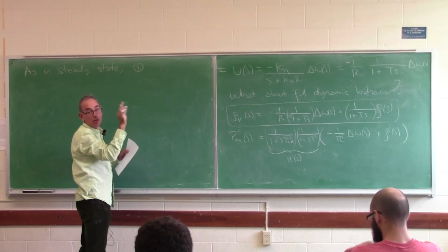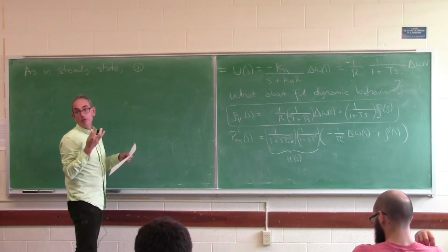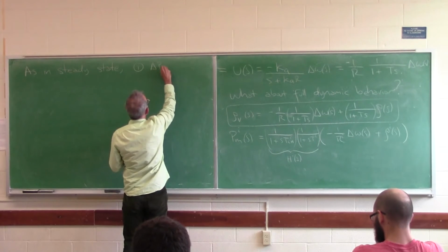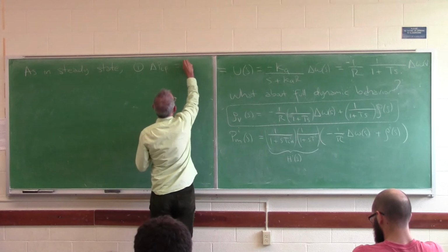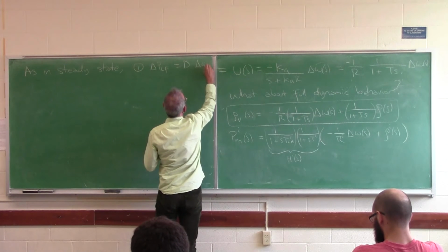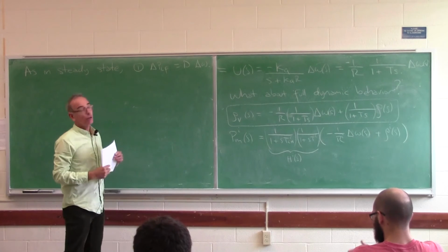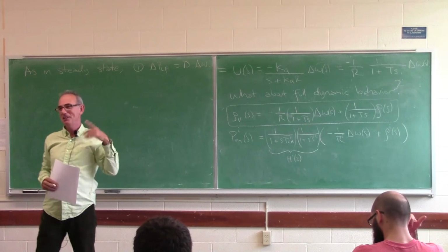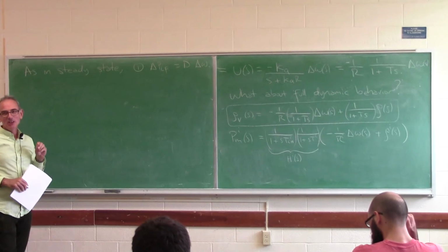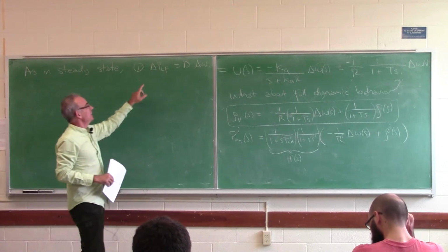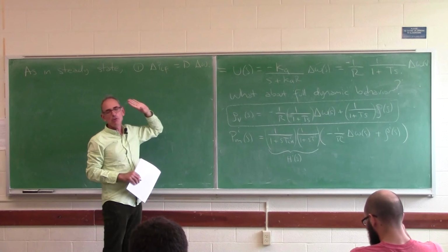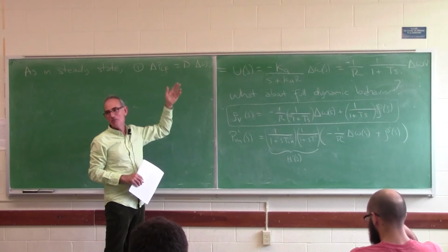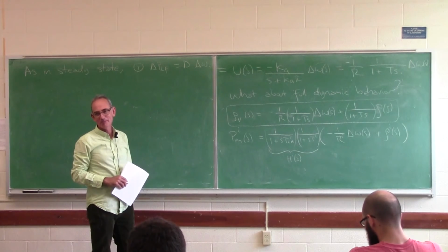So the first equation is unchanged. That there's a frequency sensitive load, which is just some constant d times delta omega. And so if this is negative, it says that there's some load that's shed, that these motors are spinning a little bit slower. And remember, each motor is imperceptibly slower, but you've got hundreds of millions of them, and so they all add up.